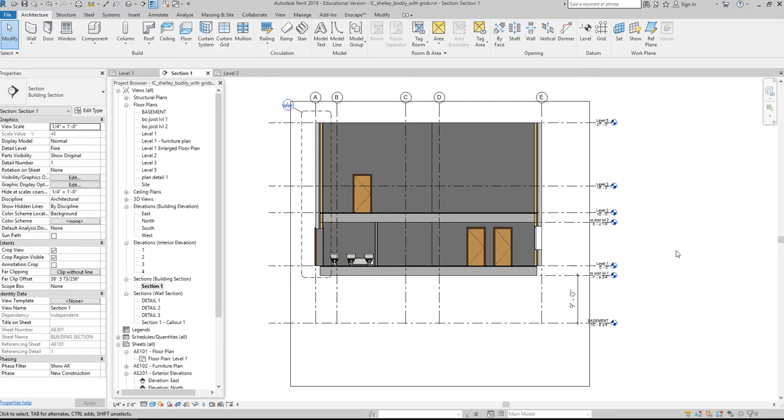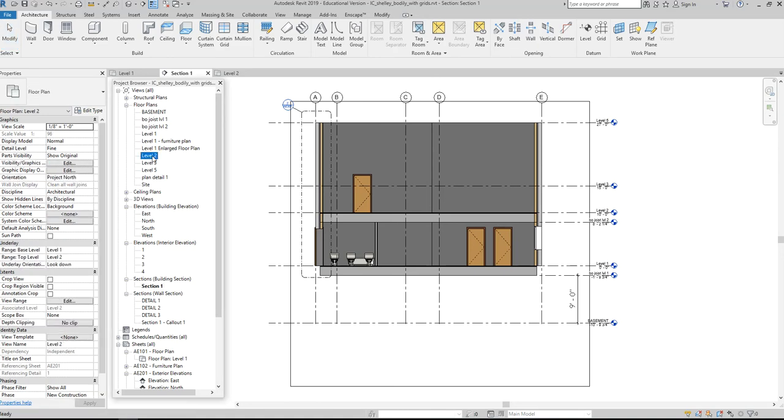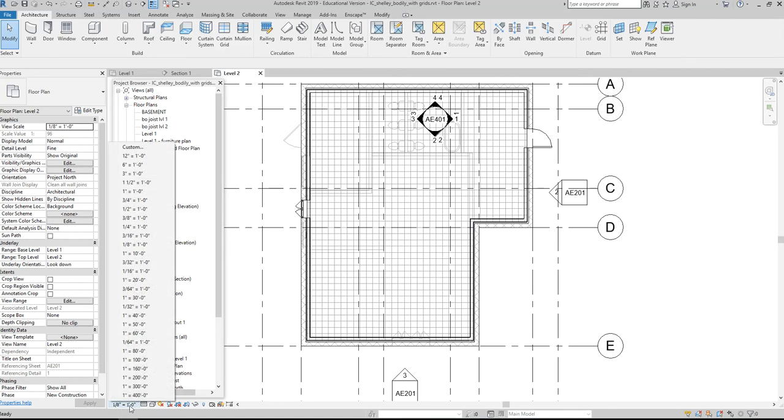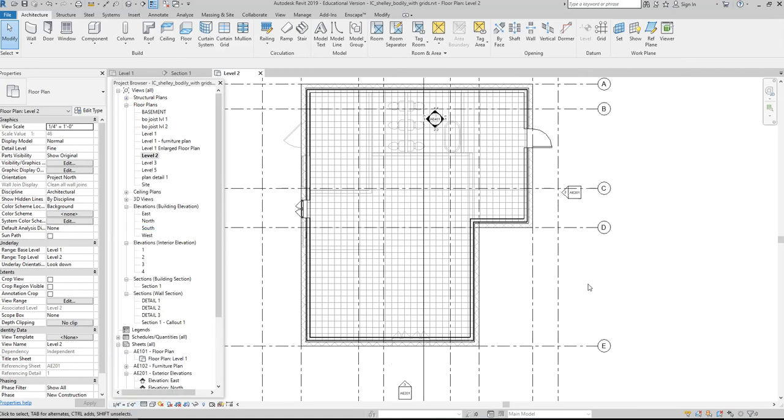One other thing I want to show you about our floors or sketch modes is that you can create openings in them. So for example, in the upper level, level 2, I know that I want to have stairs that go from the main level to level 2. And in order to accommodate that, I need to have an opening in the floor. All right. Something you're just going to have to continue to remember about Revit is that it's a built digital model, right? And so if you have stairs, the stairs don't just go through the floor. You have to frame out an opening and the stairs go through the opening, right? So the same thing with your digital model. You have to create the floor and then create an opening in the floor for the stairs to live in, all right?